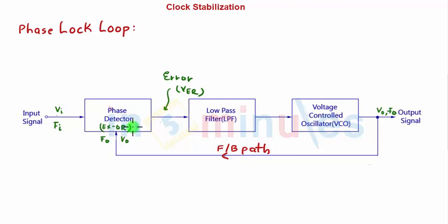And this DC level is then passed to a VCO. We just now saw the low pass filter producing a V adjust, which goes to a delay line. Now you will understand very clearly, this is nothing but a voltage controlled oscillator. The output of the low pass filter goes to the voltage controlled oscillator, correct?